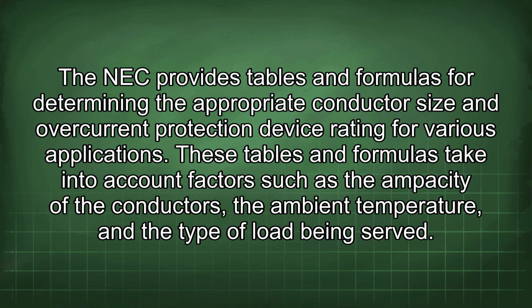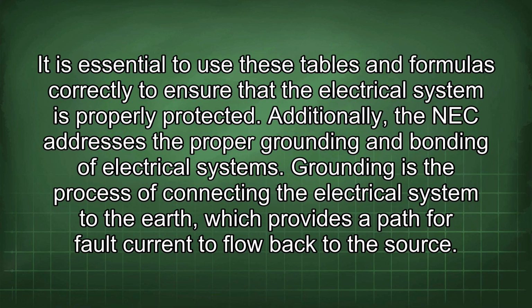These tables and formulas take into account factors such as the ampacity of the conductors, the ambient temperature, and the type of load being served. It is essential to use these tables and formulas correctly to ensure that the electrical system is properly protected.